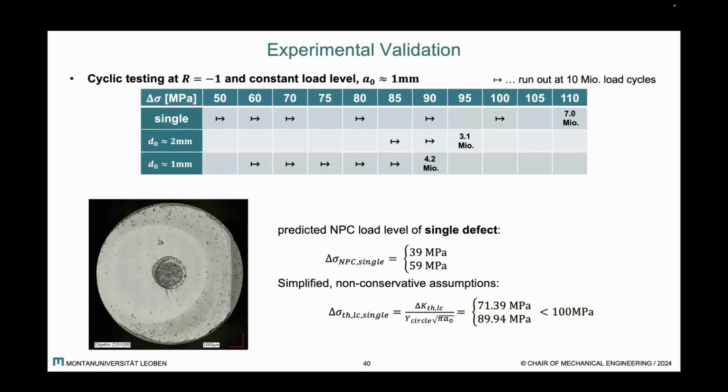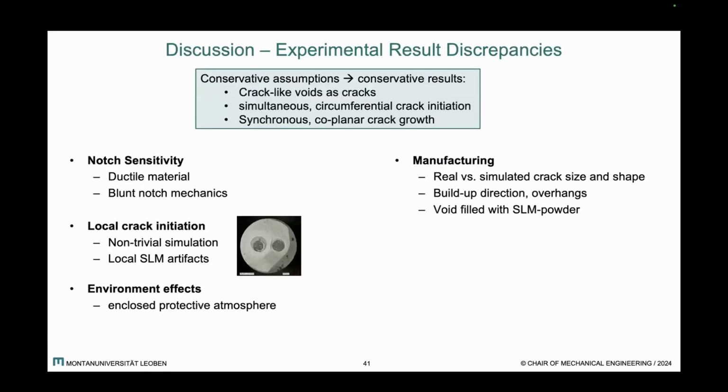The one interesting observation here is that the results lie fairly high above the predictions. Even with the conservative or non-conservative assessments of using the long crack threshold on the initial crack size for the single defect, for the different long crack thresholds, we arrive at lower load scales than we observe in the experiment. And that partially has to do with the conservative assumptions of the simulation setup,